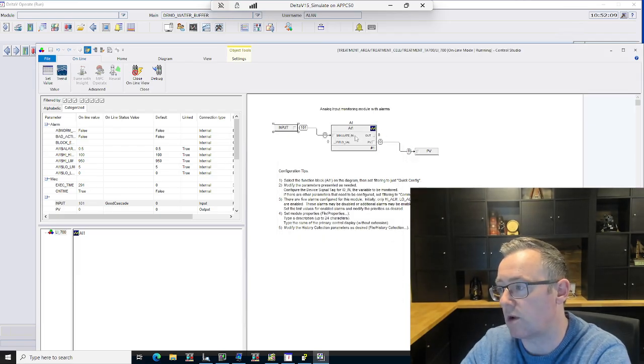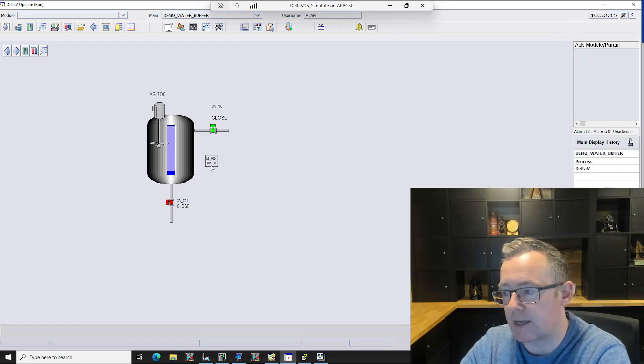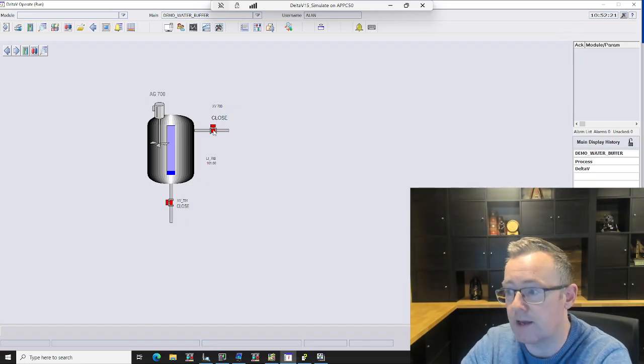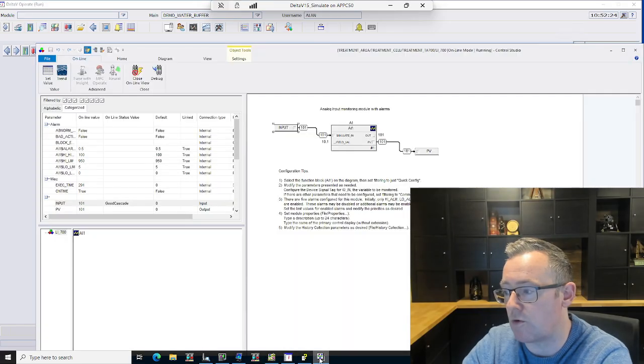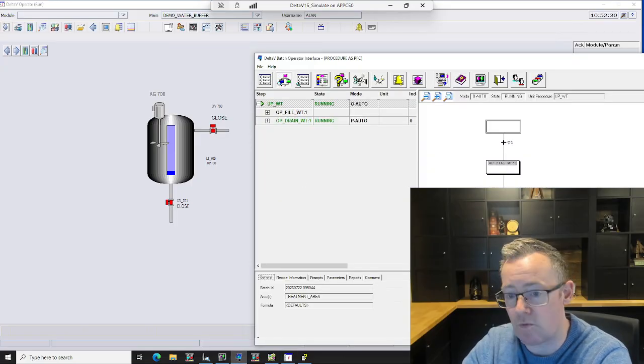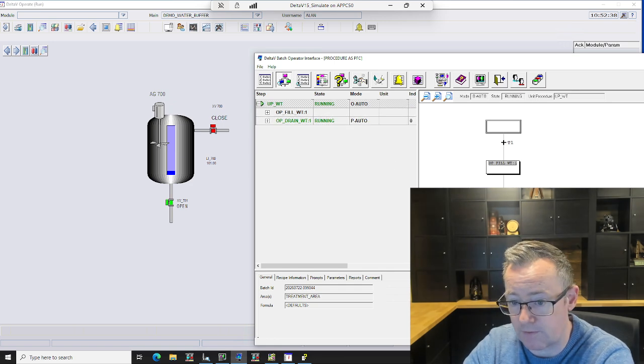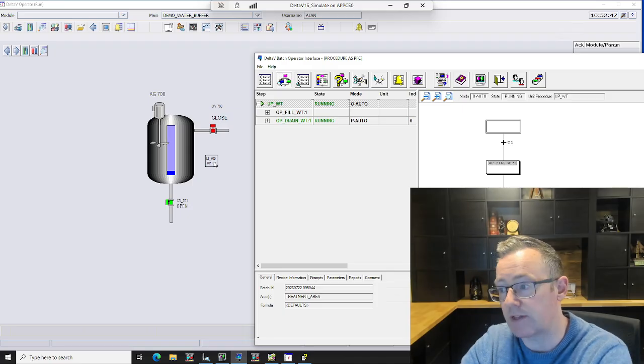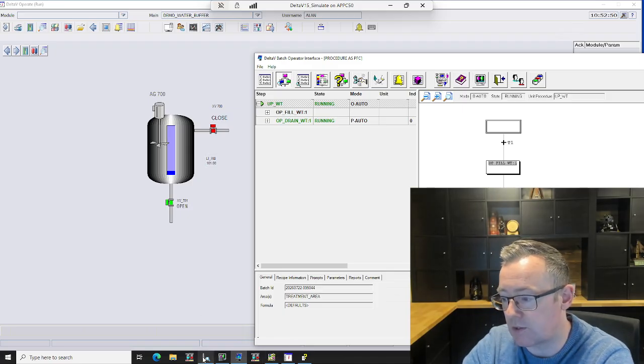And I can see that there's an actual process value that is going to update. Okay, so I can see that this has gone up right here. And then I can see that the item has closed. Okay, and basically what's going to happen now, if I go back to the batch operator interface, I'm going to see that now we are running the drain phase. Okay, so I can take a look at him. What that essentially means is inside drain, there's a small body of code, which will be there in the blog, essentially saying that we open this particular valve and we open it until the actual level sensor has gone very, very low.